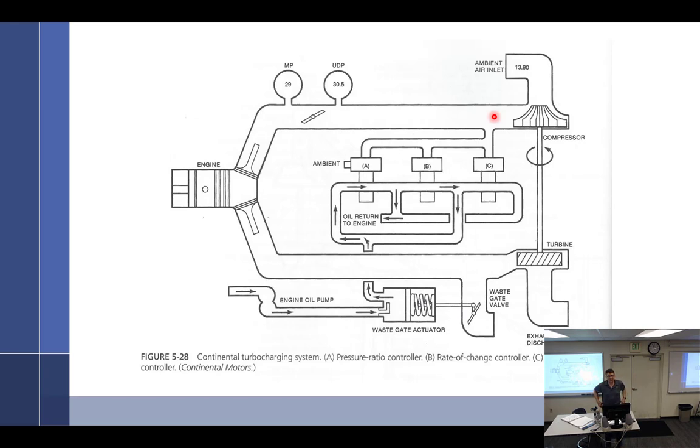So what happens is if you go very high in altitude, at some point, an engineer has figured out if you have a very low outside ambient pressure and you're pumping this much air into the upper deck, then you're going to have too much of a split, which is going to mean the air is going to be too hot, if nothing else. And you're going to just see the design limits. You can start blowing off hoses. So that will take care of that.